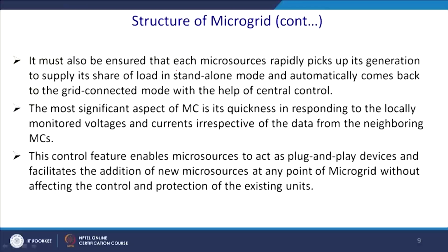It may also ensure that each microsource rapidly picks up its generation to supply its share of load in standalone mode and automatically comes back to the grid connected mode with the help of central control. The most significant aspect of MC is its quickness in responding to locally monitored voltages and currents, irrespective of the data from the neighboring MCs.